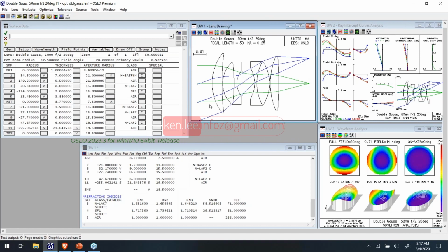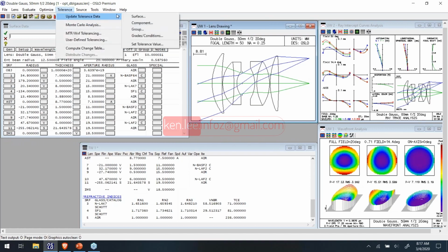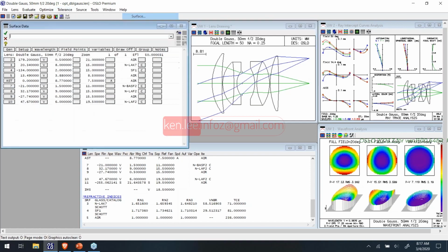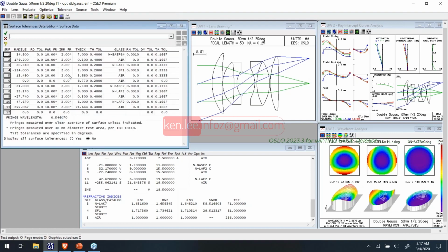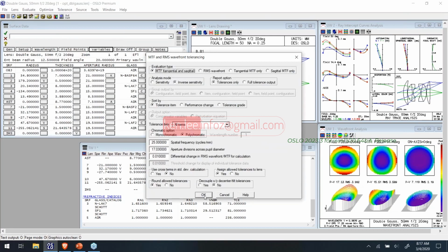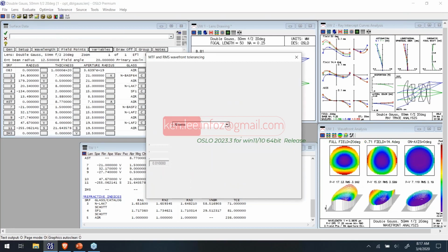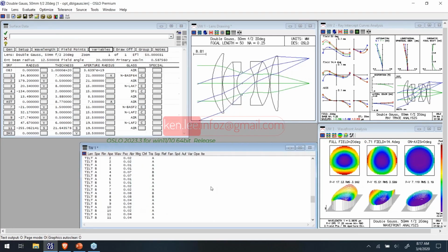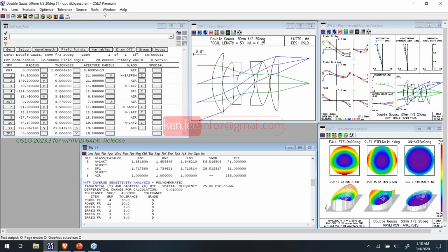So it's quite good at different tolerancing steps. There are some spreadsheets in here that work on different sort of tolerancing factors. Right now, this one hasn't had numbers assigned, so it's set up to some old ISO 10110 default types of numbers. I could show, for example, you can run this, which would be an inverse sensitivity analysis, and it likes to give out lots of numbers, but we have a lot of flexibility.